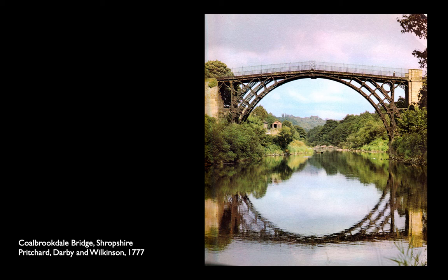Pritchard and Wilkinson basically are what we would think of today as the engineers, right? Designing both the structure and thinking about the way to build it. It's not a particularly sophisticated structure, right? It's a semicircular arch, and we know by this point that what you really want is a catenary arch or something more of a parabola. But nevertheless, this is proof of concept, if not of a really innovative structure, of a really innovative building system.